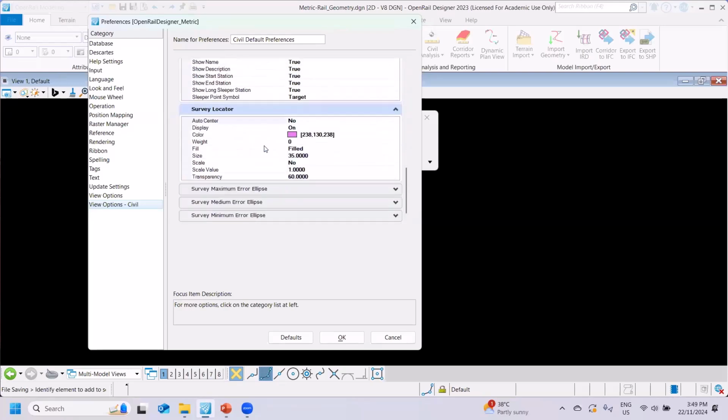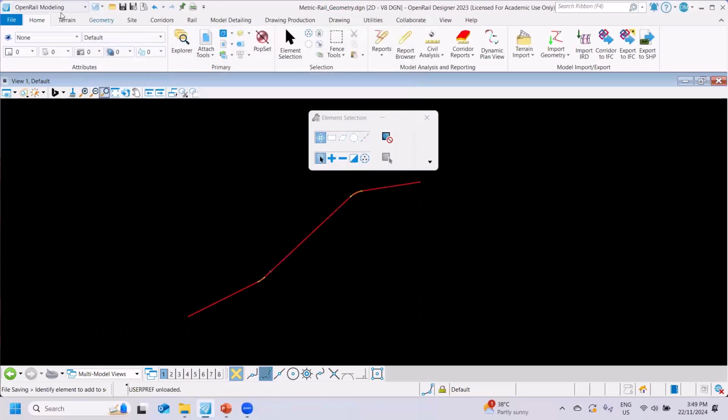All those different elements that you want to control in the preference file that we load in the case of PowerRail Track can be seen over here, and we can optimize it according to our project. And if you don't want to do it, you can always use the default settings and make the best use of it. So you have the option to set back to defaults. I'm going to say cancel.